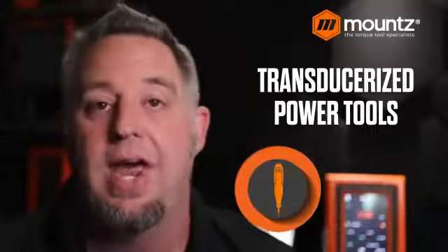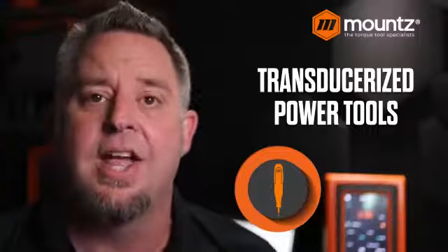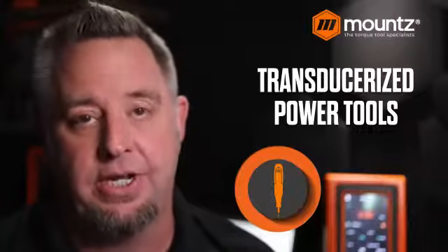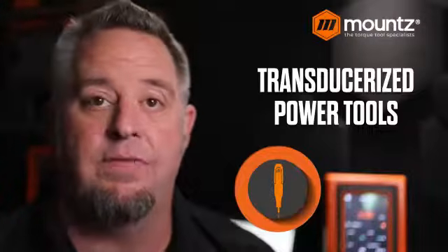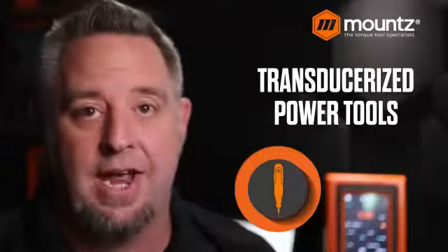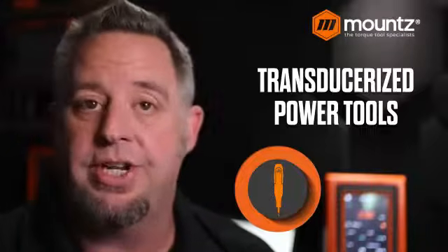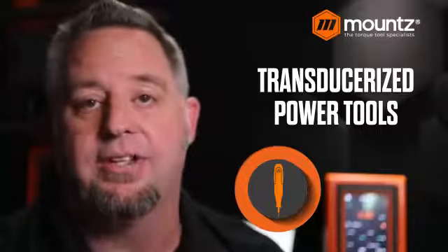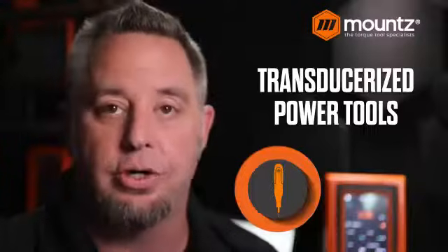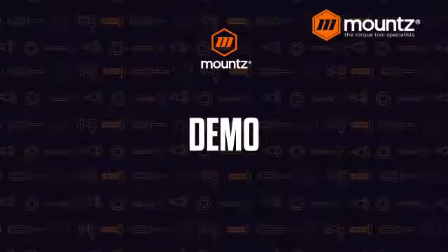And so we have a transducer that is built into the tool, and this will allow us to look at a particular rundown of a particular joint that may help, again, looking at a problematic type of application where we're seeing some inconsistencies. We could take a look at the joint characteristics using a transducerized power tool. And so let's go ahead and take a look at what that looks like.